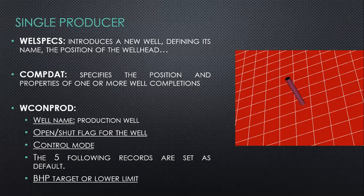To obtain a single producer well, all the previously detailed sections, including the RUNSPEC, GRID, PROPS, SOLUTION, and SUMMARY, will be part of the input data file to Eclipse, but with one additional section, which is the SCHEDULE section. This section is the final section in an Eclipse input data file.